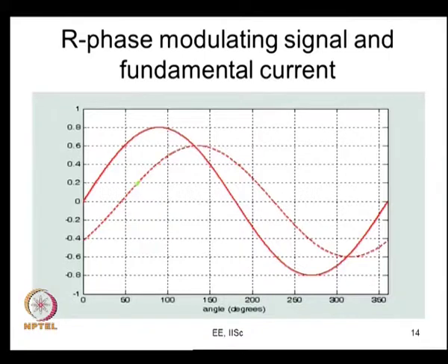So, how would the switching energy loss vary? It would vary in the same fashion as the current varies. So, let us say this is our switching energy loss. At the current zero, it comes down like this, and further it goes up the same way.